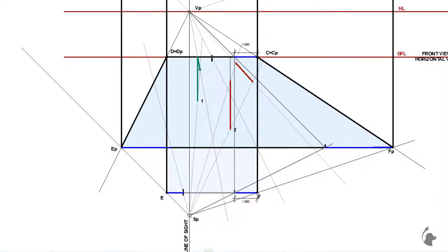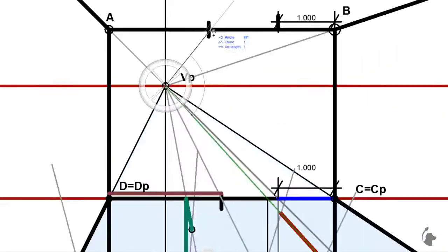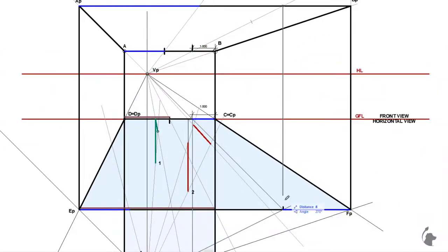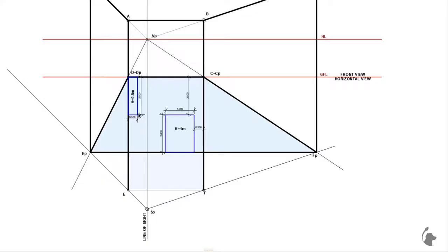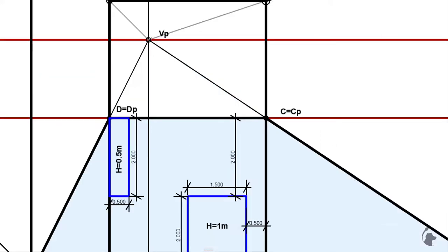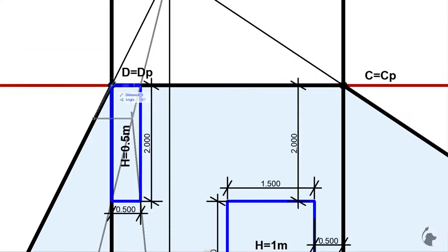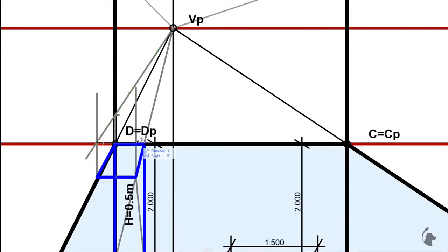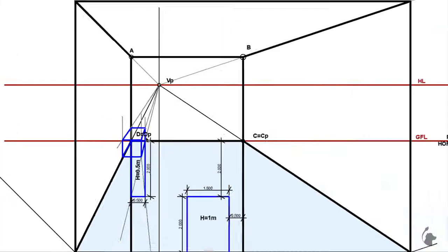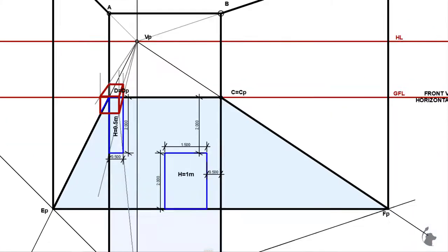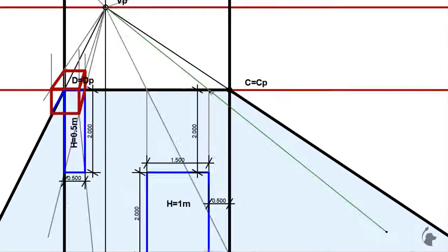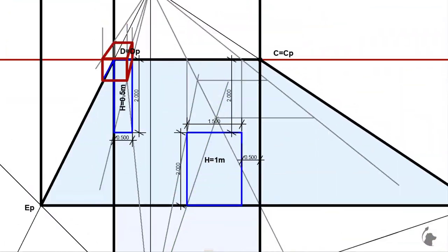Today we're gonna learn how we can take precise dimensions and put them into 1-point perspective so that the result is exactly what you would see in those conditions in a real life environment. So, at the end of the lesson, you'll be able to take any measurable object and draw it from any angle at any desired eye level and from any established distance from it.